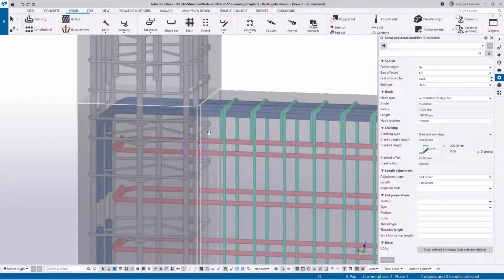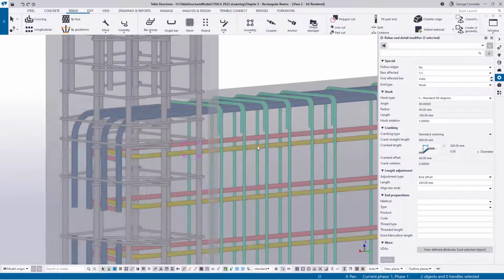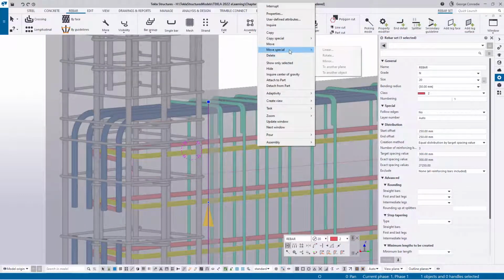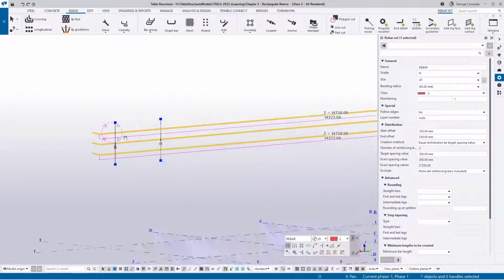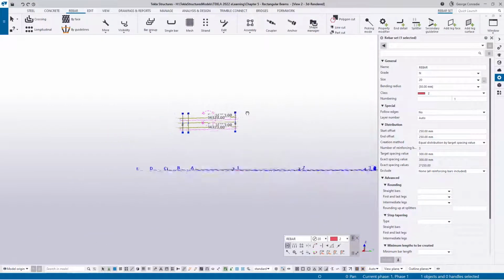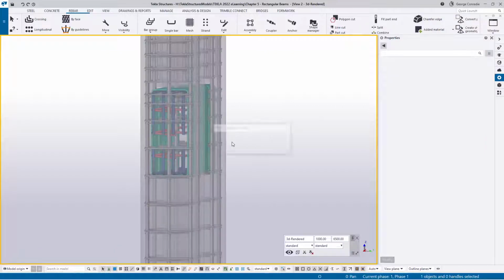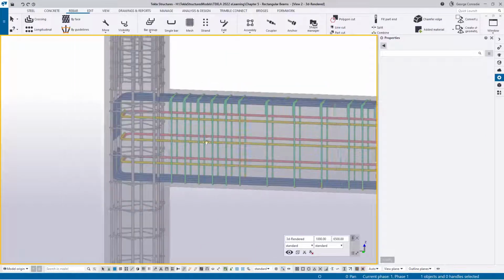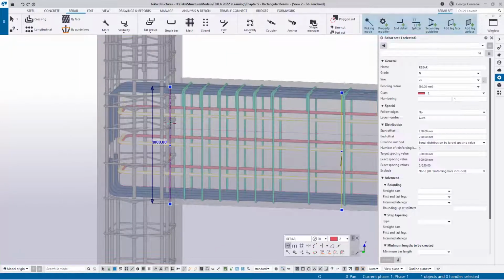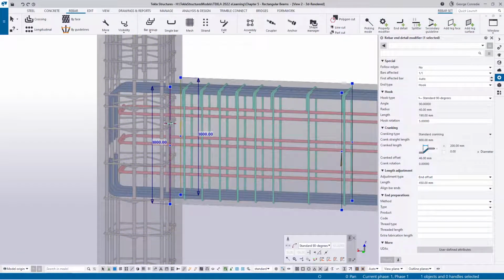The only difference now is that if we look at this bar, just click on that and say show only selected. This bar should be slightly twisted unless the mirror has fixed it up for us. You can see this bar is twisted. The one hook is pointing up, the other one's pointing down. So the way we fix that is we just come over to this side, click on the bar, click on the other bar, click on this modifier, Control this modifier, so we've got the settings for both of them, and change the 5 to a -5 so they go down the same route.